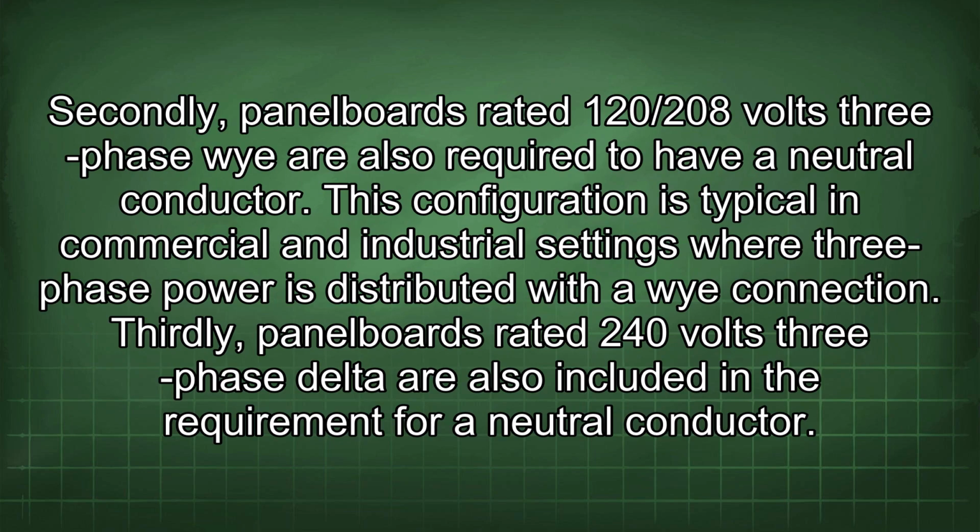Secondly, panel boards rated 120/208 volts 3-phase Y are also required to have a neutral conductor. This configuration is typical in commercial and industrial settings where 3-phase power is distributed with a Y connection.